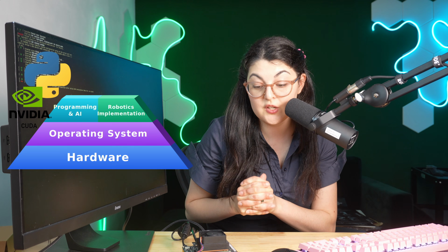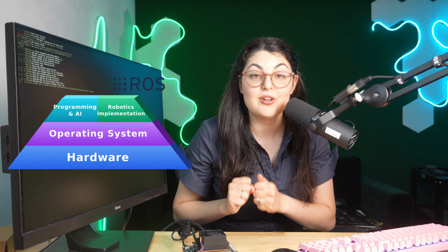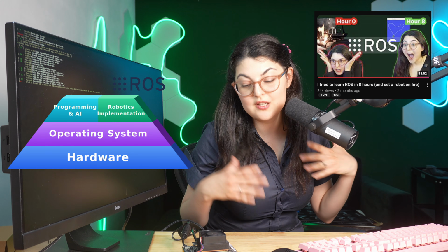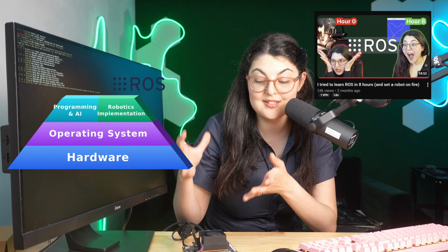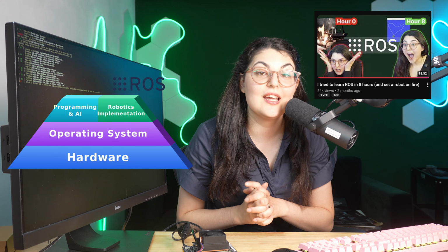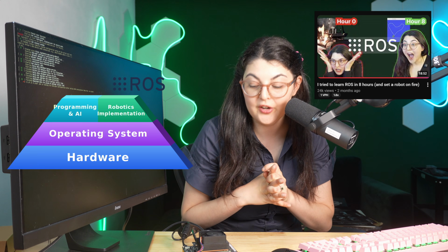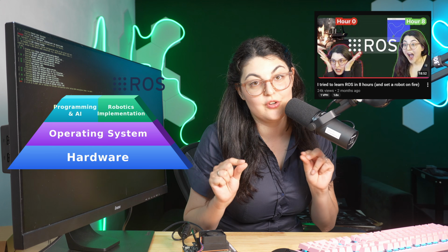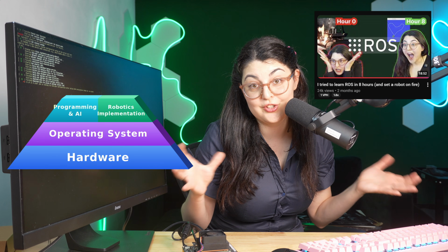Then we want to set up everything that has to do with the robotics hardware. We're talking about installing the right ROS version, which can take a little bit of time, especially because although this is of course going to be running Linux and Ubuntu, it is running it in a particular Jetson kind of way. So I'm a little scared that there'll be some issues to iron out there. And we also want to set up the Isaac Lab and Isaac Sim, which also only work with specific versions of ROS. So we have to find a common denominator that works smoothly with everything. And finally, I want to see how this deals when interacting with actual hardware, and perhaps already set up the foundation for what we're going to want to run later, which is the SO101 ARM projects.